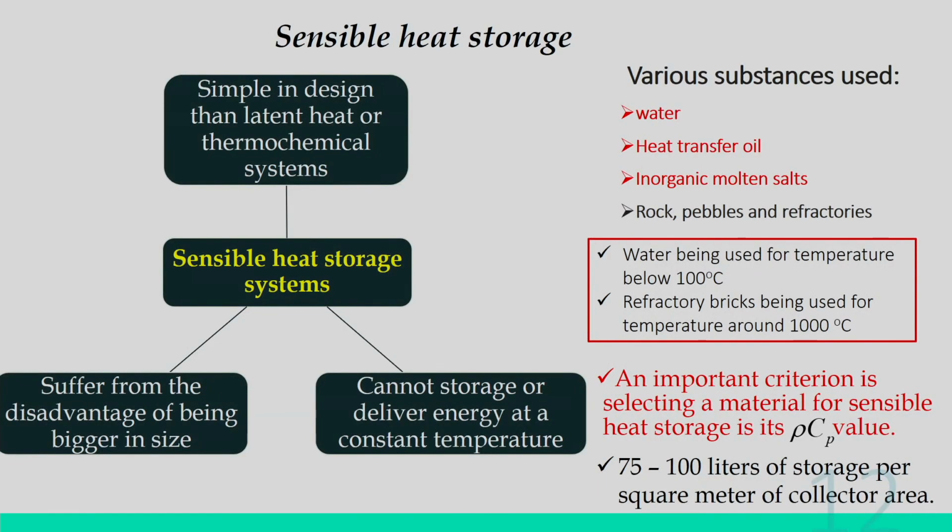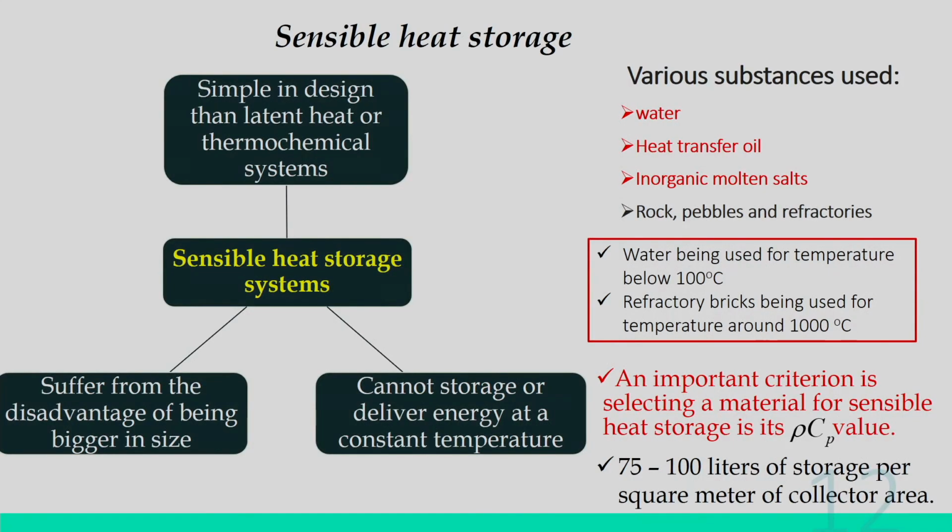Now, coming to the sensible heat storage system, which is simpler in design than latent heat or thermochemical storage systems, but it has some disadvantages, like it requires a bigger size of system, and it cannot store or deliver energy at constant temperature. That is the major drawback.